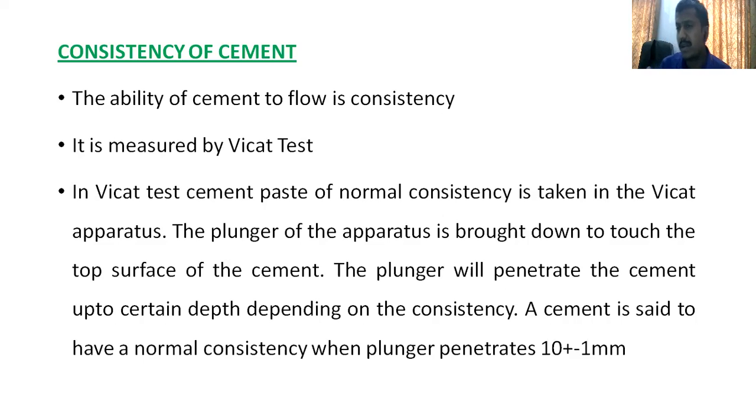The cement paste is flowable in nature, but it is not flowing very fast. It is in a semi-liquid, semi-plastic stage, not fully liquid, not fully plastic. So how much water do I require to make that paste a workable, good paste? That is what we are going to determine. For this, we are going to conduct one experiment, which we call the consistency test of the cement.